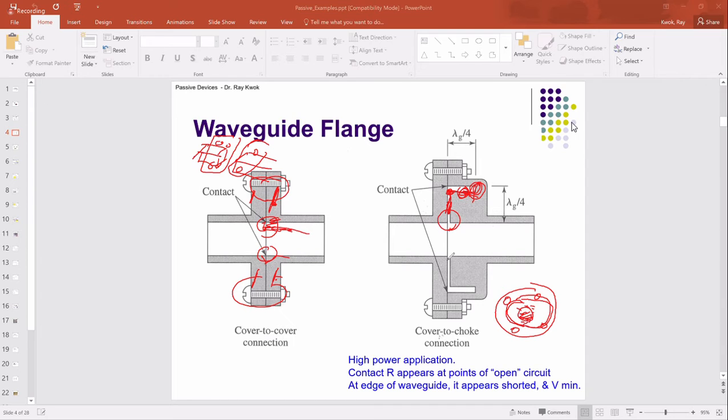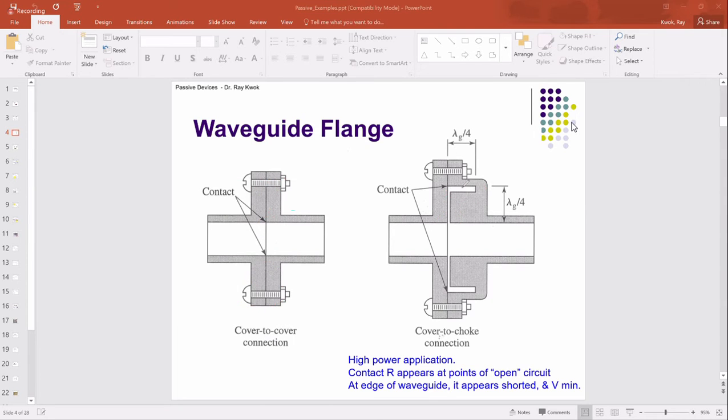But the groove and the recess, they both have to be cut precisely to make a quarter wave. Oh yes, this has to be modeled. I mean, most likely people will model in HFSS, make sure that works for the frequency range that they want, right? Yeah.